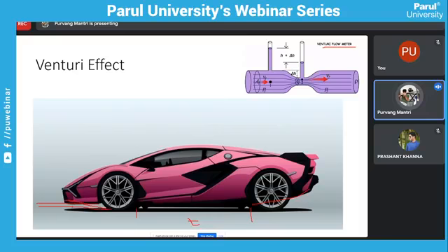As the cross sectional area is reduced in the front end, the air tends to move fast from beneath the car. As soon as it hits the divergent region, it comes back to its original velocity. The velocity in this region is high, and this can be achieved because of the front bumper splitters and the diffusers.